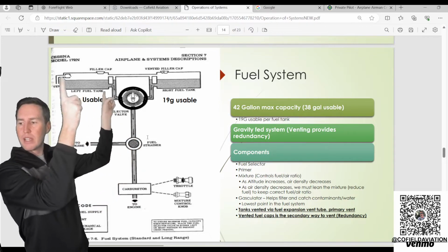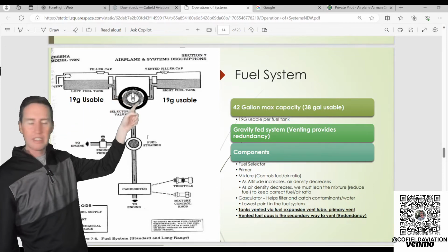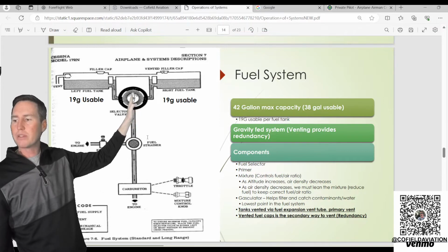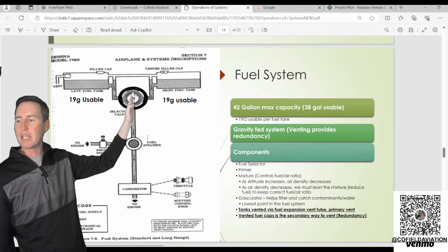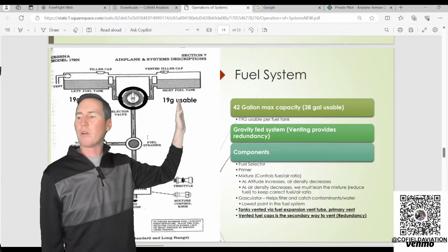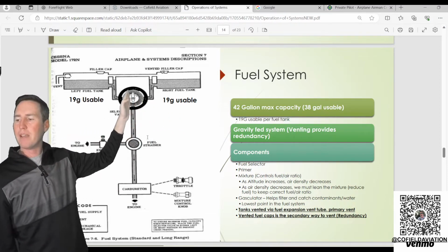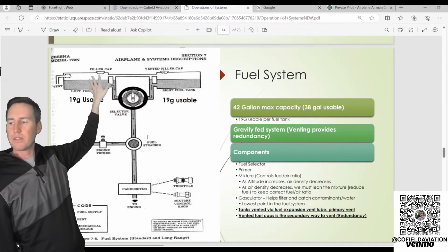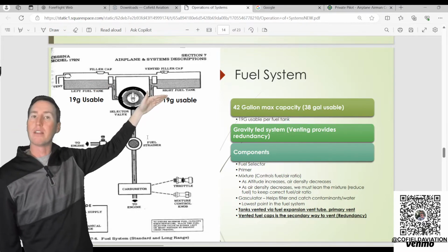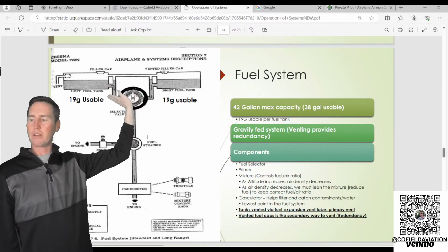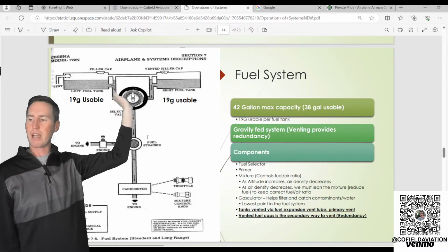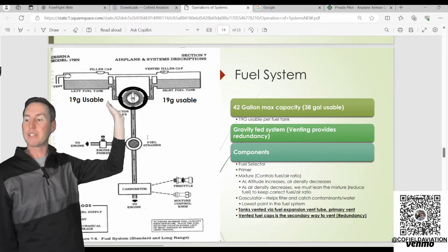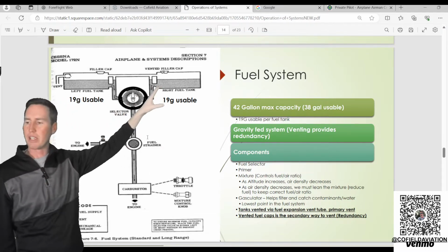So the fuel flows out of the tanks and then to this fuel selector right here. The way it's sitting right here is on both, so that means it's taking fuel out of both tanks. That's where you're going to run this thing 99.9% of the time, okay? If you made the selector point to the right, that means it shuts the fuel off to the left tank and you're only running on the right tank, all right? If you then conversely put that fuel selector to the left, that means that you're running on just the left tank and you're shutting off the right tank.